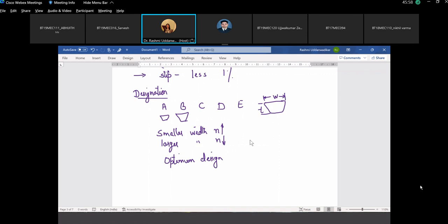So even if one fails, it calls for replacement of all the belts, and so the cost also increases. If you replace only one, and one belt is new and the other 3 belts are old, then the power distributed is not uniform. The force which the belts are transferring is not the same.